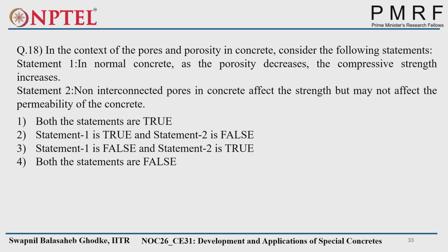Next question is in the context of the pores and porosity in concrete. Consider the following statements. Statement 1 says in normal concrete, as the porosity decreases, the compressive strength increases. And statement 2 says non-interconnected pores in concrete affect the strength but may not affect the permeability of the concrete. So, what will be the answer?